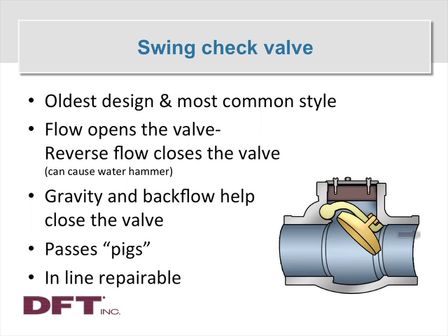This style of valve that I'm showing here with a bolted bonnet type, this pressure seal bonnet may not apply in what I'm about to say, but for the bolted bonnet valve, the disc will swing high enough that you can pass a pig through the valve. And you're wondering, a pig? The little critter with the curly tail and the squishy nose?